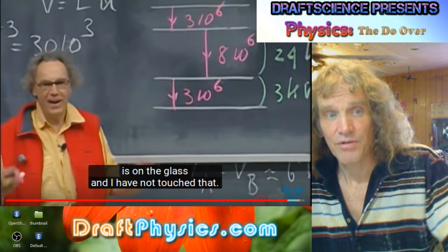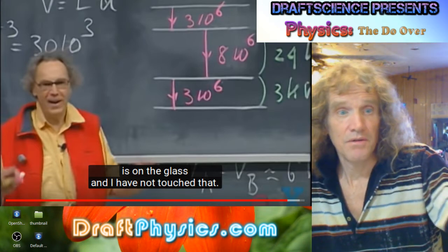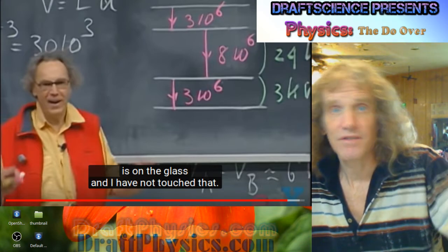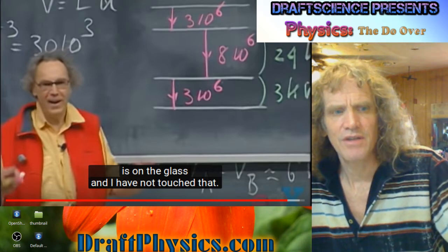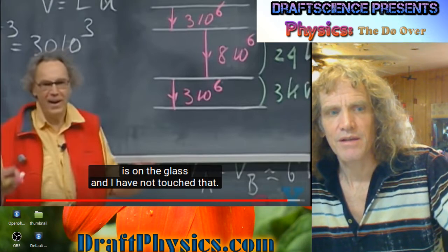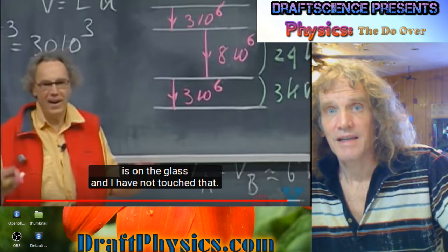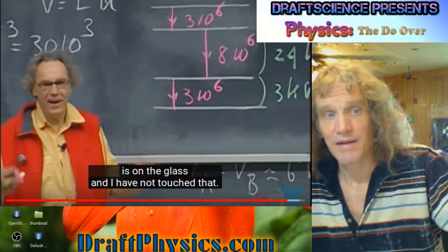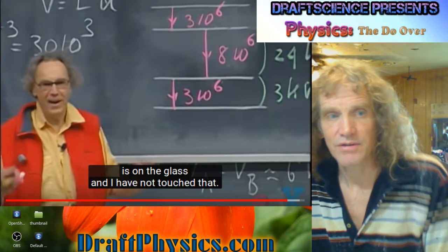So as long as I have more than you, I'll give you everything I got. So it gives the glass 80%, 90% of its charge, because it's not until it's given up 80% of the charge that the voltage gets low enough between the glass and the copper for the copper to say, you're now below my breakdown voltage. I can't break down anymore. At 3 kilovolts, I can't break down anymore. I can't send you any charge.